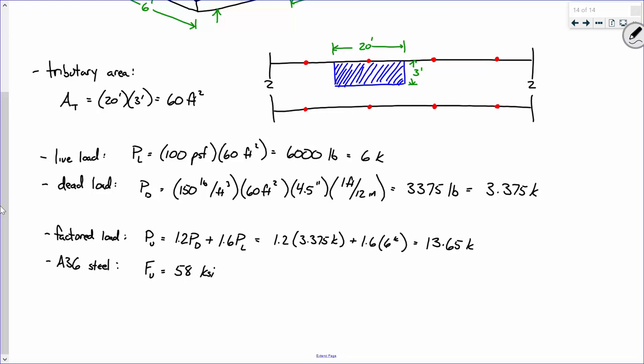And here's why. Back in the 70s and 80s, the steel industry was telling every structural engineer and architect and what have you to resist earthquakes properly, use moment frames. In other words, use those rigid frames as opposed to the ones that are braced, because the perception is that moment frames would allow more movement, which is really an advantageous thing in an earthquake, because more movement and more ductility is more desirable.